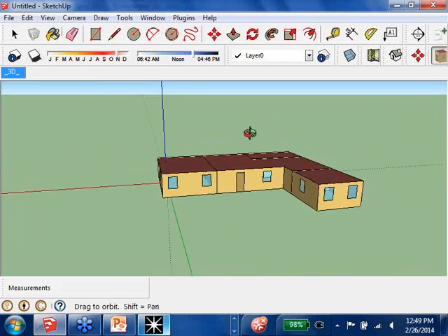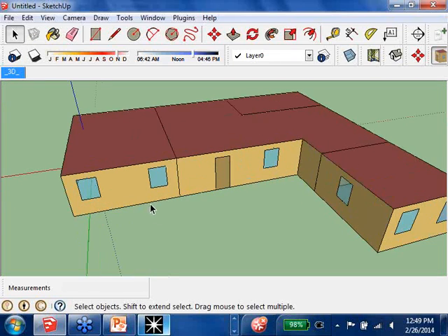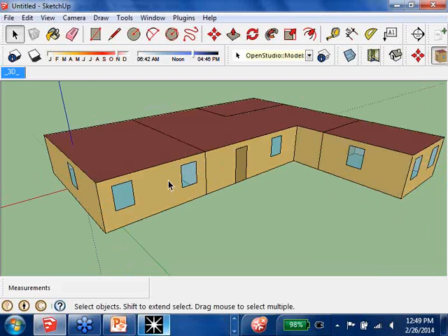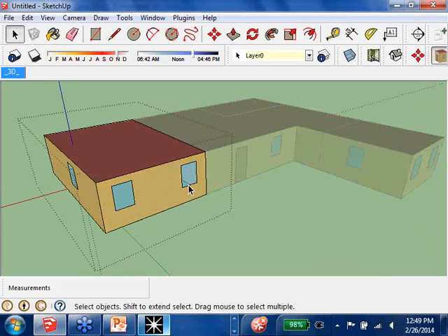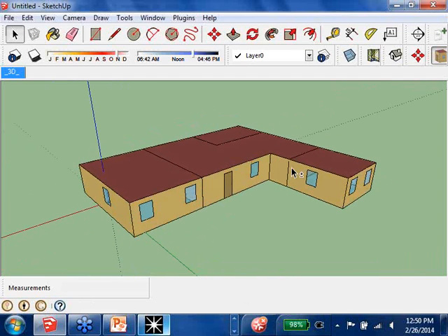So you can see this does not have the shading surfaces, and the floor is missing. Everything else is simplified and would be very easy to use for a daylight model. Again, there's flat planes instead of the thicknesses for the walls, but it's kind of harder to work with than Ecotect. So for the most part, I feel like Ecotect works really well for GBXML. Everything's simplified. Everything seems to come in fairly easily. It's easy to export. For DWG and DXF, it's a lot easier to work with in SketchUp because of that component property, if that makes sense.